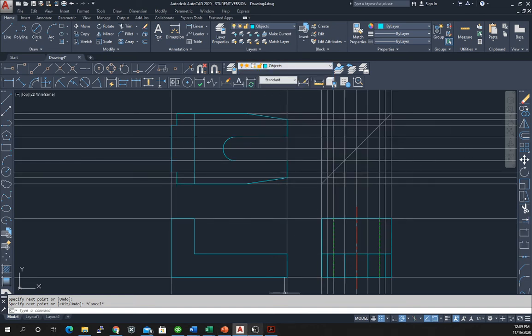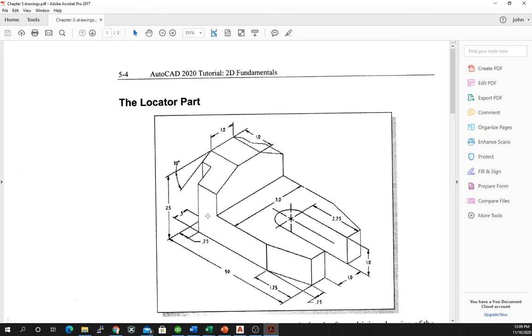And if you remember, I talked about that diagonal, but we haven't put it in yet. So let's put that diagonal in. So we want to put in a 30-degree diagonal coming from 1 inch in. And we can use the construction lines to do that, or to start that. And we can combine that with tracking lines.